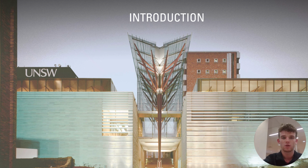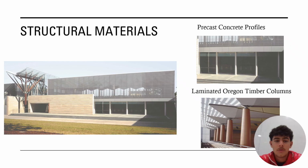In this presentation, we'll examine the key materials used, assess their performance and sustainability, and then propose more sustainable alternatives. The John Niland Scientia building uses a clear set of materials across its main components, starting with the structural materials. Precast concrete profiles woven through the sandstone podium, forming horizontal courses, louvres, and balustrades. Laminated Oregon timber columns, 12 in total, providing the main vertical support for the foyer roof.